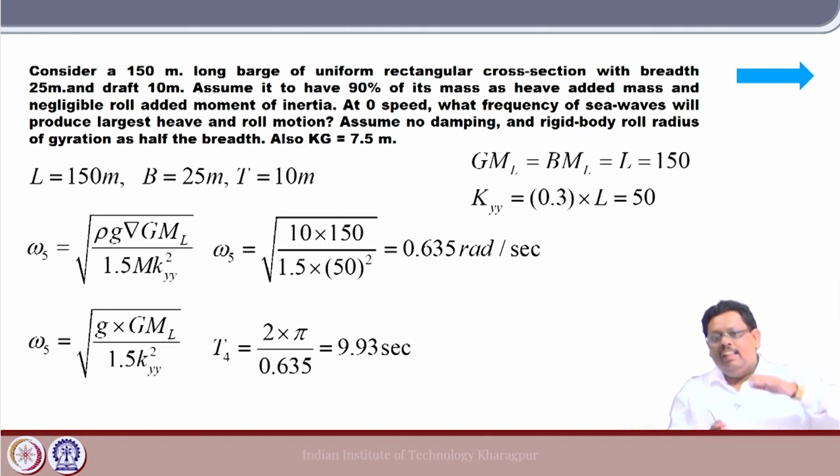Now, you see, in both situations heave and pitch are excited by the same wave, and both tend to get to the maximum amplitude. If both come at the same time, it means that when it is heaving maximum, at that time pitching is also maximum. Now, you can see how much bending moment will come in this particular case. So, that is why this phase is also very important.